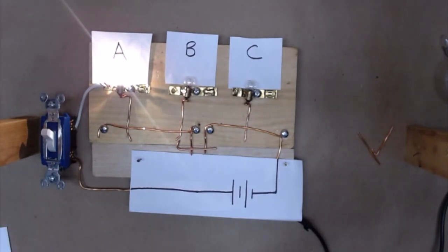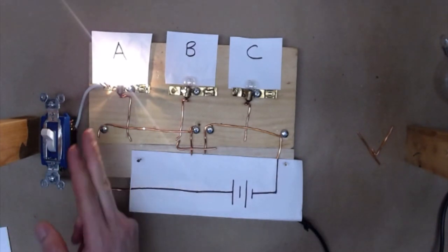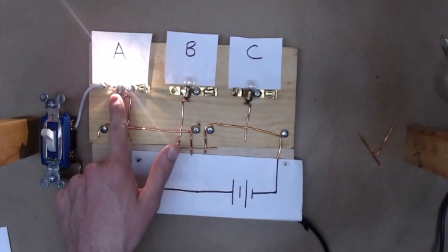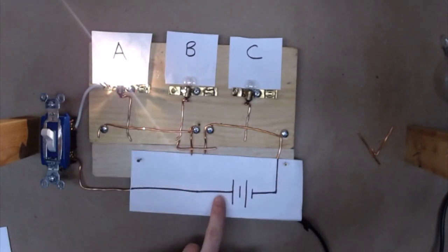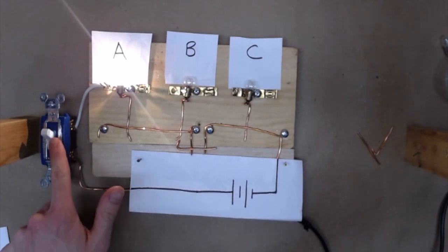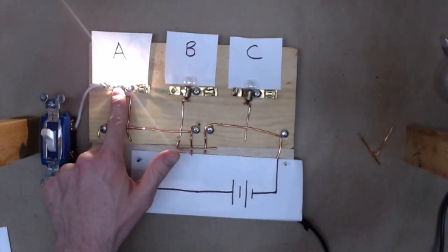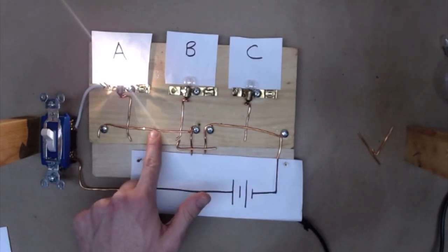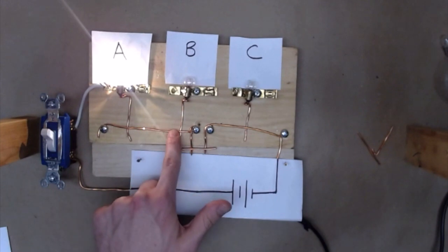And here, when I flip it, we see with this closed circuit that bulb A is illuminating at the same brightness as it was in the previous demonstration. Well, if it's illuminated at the same brightness as the previous demonstration, knowing that power is equal to current times voltage, and knowing that the voltage source has stayed the same, we can infer that only bulb A is in this circuit. And sure enough, if we follow the path through here, up to here, to here, through the brass sheathing, going down to the bottom of the bulb, through this copper to here, recall why I can't go this way, through the copper, right?